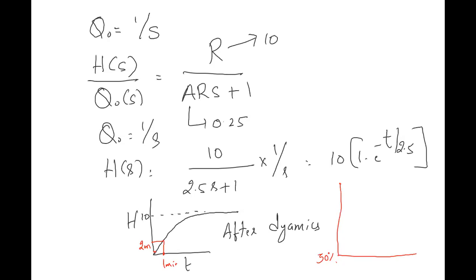30%. So now slowly the valve opening will also be calculated exactly proportional to this one, so that the level will never feel the effect of disturbance. This may be, let's say, 50%. How water is going to be accumulated is studied using the transfer function, and accordingly the valve will be